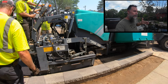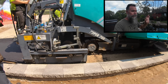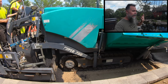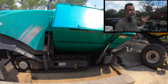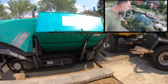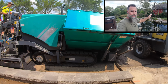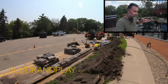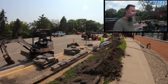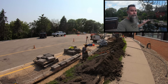And I would always go back to those specs and say, whoa. The specs clearly say that no equipment is to be allowed within 3 feet of the backside of the retaining wall, and heavier equipment is supposed to be within 10 feet of the backside of the retaining wall. And I stood on the actual retaining wall itself and told the guy to back off, and they wouldn't listen. And it's not my job as one subcontractor to control another contractor's work. We cannot do that. And so eventually that whole lawsuit against me was dropped.